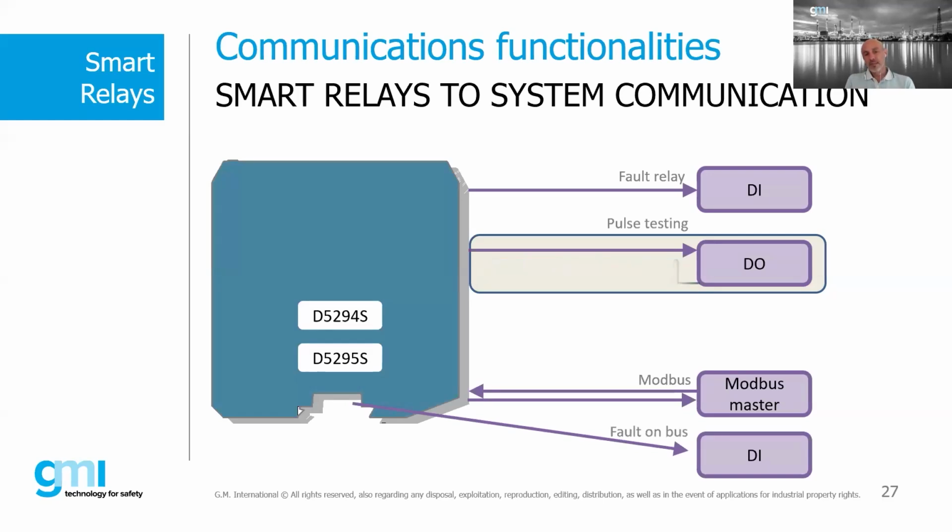So I would say that in this case, those failures could be dangerous. And if you don't detect them because you don't use line monitoring, those are undetected. So those are dangerous undetected. But if you are able to monitor them, you can detect them. So in this case, they become dangerous but detected failures. So they change completely the safety value of your system.